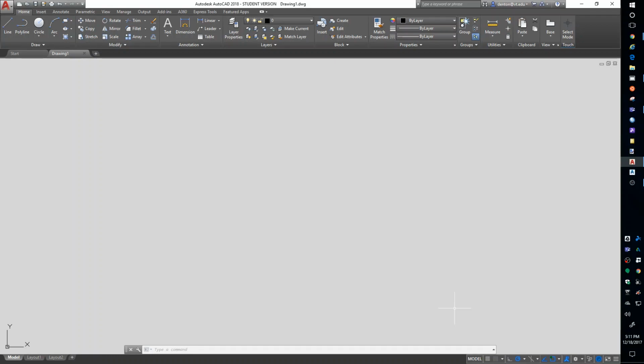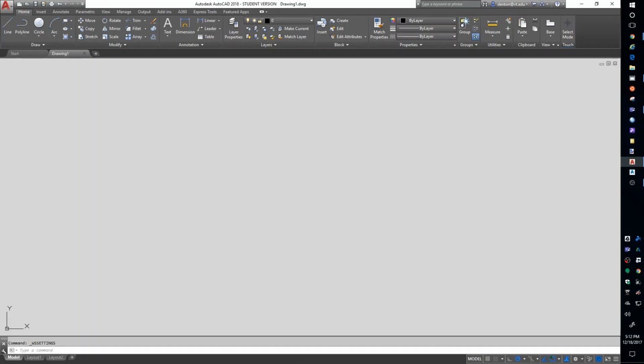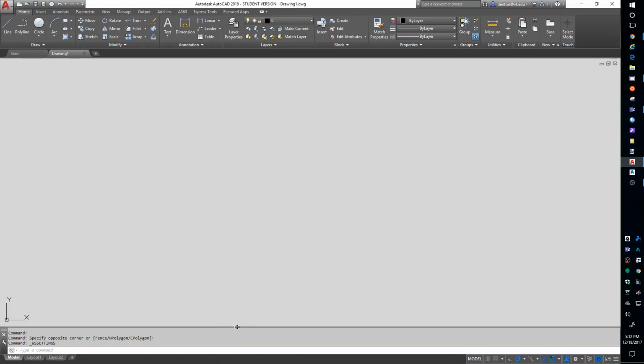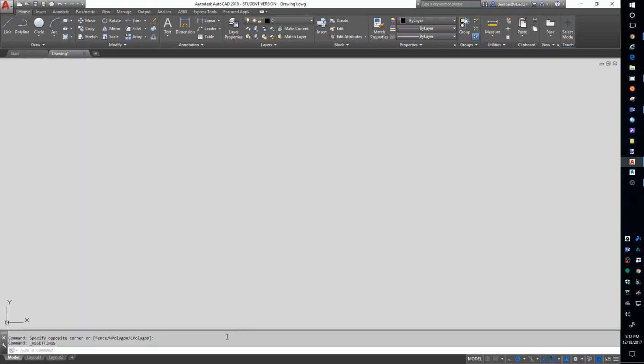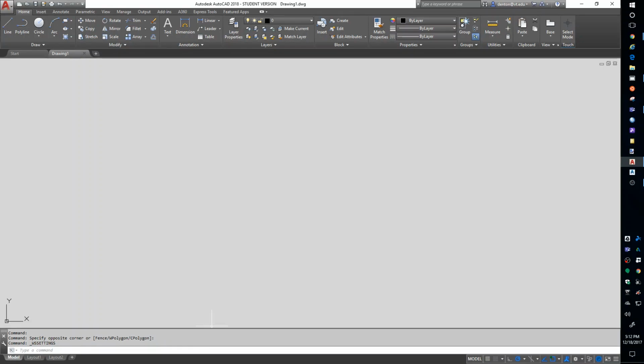On the left end of this is an area you can grab the toolbar, and if you bump it into the bottom of the screen, it'll spread out across the whole screen. Let go of it, and you can adjust it taller. I like to have at least 2 or 3 command lines visible. This is a couple lines of command history that you are in control of.